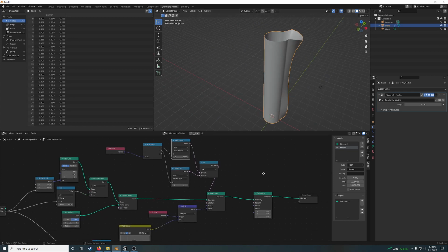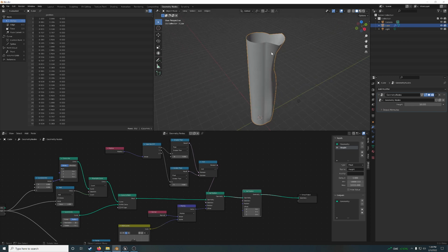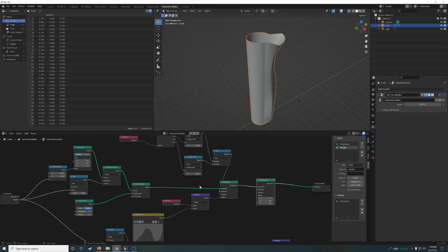Now here's where the normal maps get all jacked up, because these faces along this edge will have a normal straight towards you instead of out the direction it should be. So you'll have to do a transfer attribute, and then do the normal as the attribute, index, and vector. So you'll want the normal as the attribute.